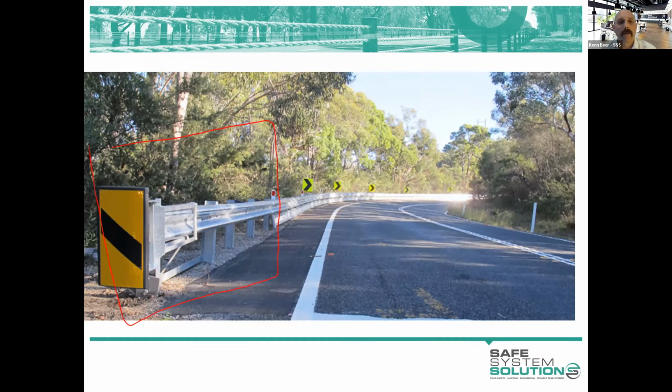That's our end terminal. It's an ET 2000 Plus, I think. So not one of the MASH ones, but it doesn't have the underrun protection on it. Now, the reason for that is that nobody's tested an end terminal with an underrun protection attached to it, and it hasn't passed the test. So we don't know how it would function. It could potentially compromise the functioning of that very intricate system in its own right. So you don't add the underrun protection to the end terminal.